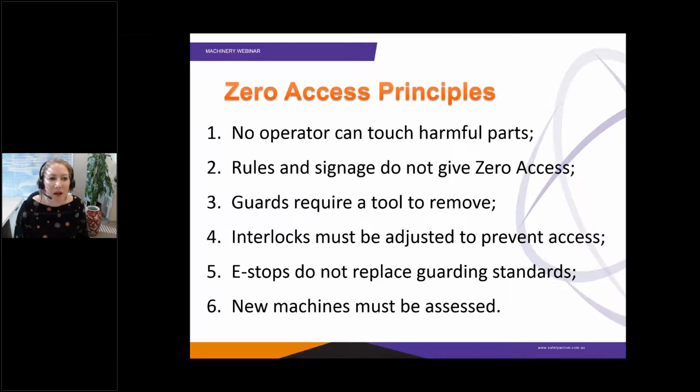Number 5, emergency stop buttons do not replace the zero access guarding standards. And number 6, even new machines often do not fully meet the zero access standards. In fact, they often don't fully satisfy AS 4024. So it is important to specify these standards when you're purchasing new equipment, and then to conduct risk assessments when you receive the equipment.